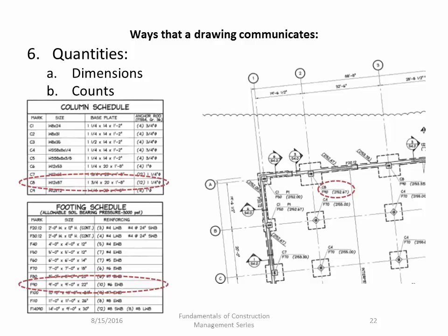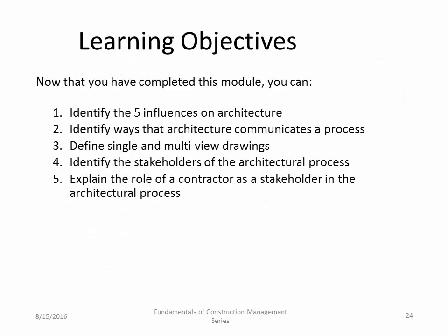And we see the designation of the concrete footing being an F9.0, that is paired with a column C8 above it. And so we know exactly how many different pieces of re-steel need to go into those footings, every type of footing that is an F9.0. But we also see, because often our role in this is to place anchor bolts for the columns, the anchor rod designation above that needs to go into place so that the steel fabricator and erector can put the steel column in place.